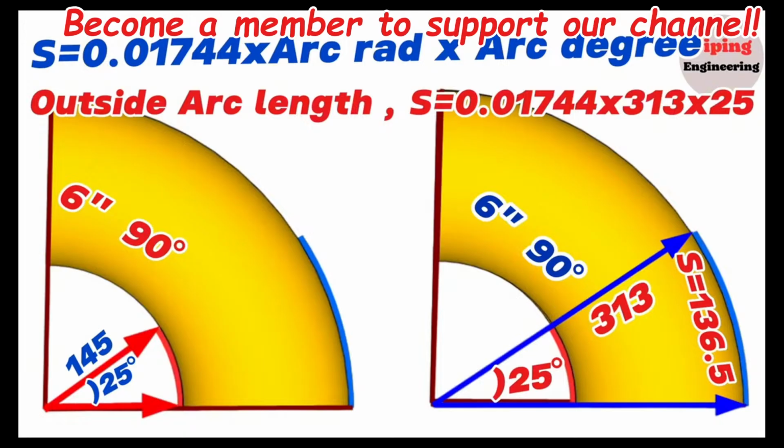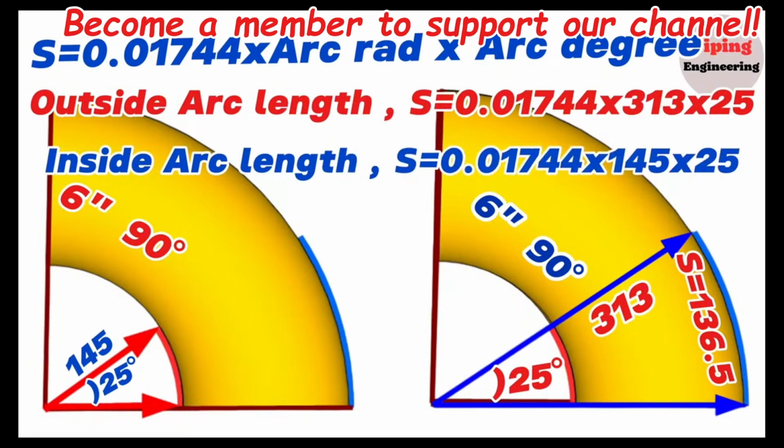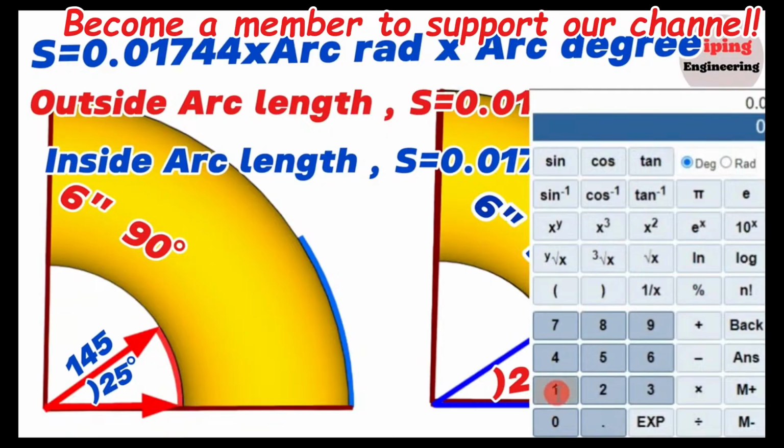Now let's calculate the length of the red color arc on the inside of the elbow. So, the length of the inside red color arc, S, will be equal to 0.01744 multiplied by the radius of the arc, 145 mm, and the degree of the arc, 25 degrees. Using the calculator, we find that 0.01744 multiplied by 145 multiplied by 25 equals 63.